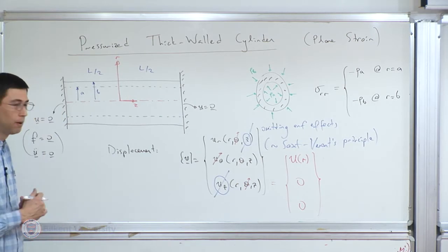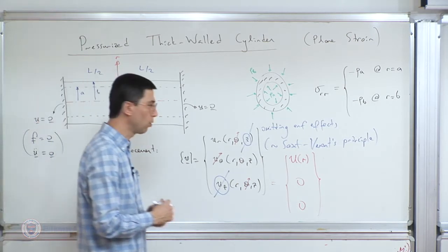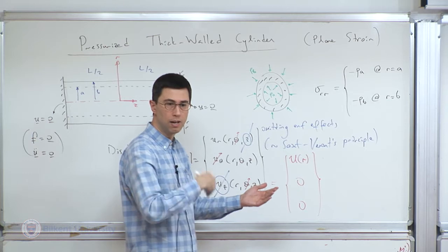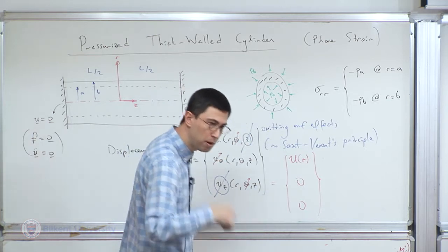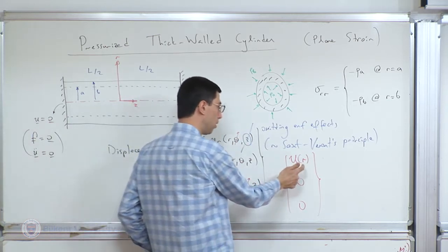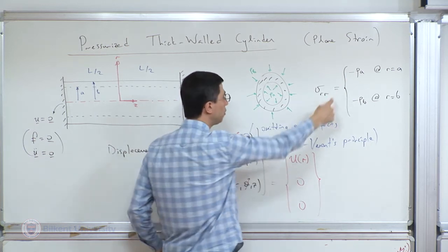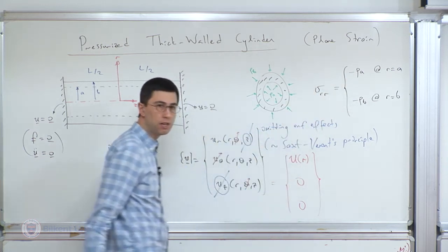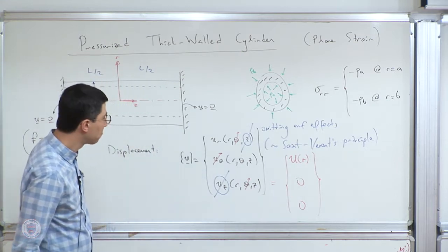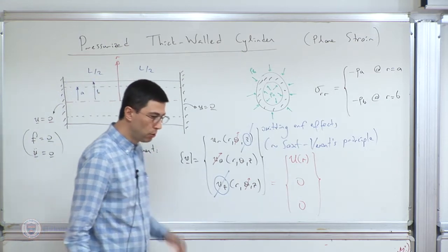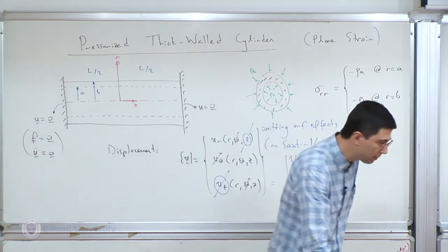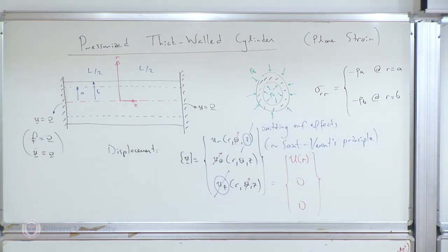This is the type of displacement that we would like to solve for. I'll calculate the strain, calculate the stress, invoke equilibrium, and thereby close the loop to find the general form of U. Then we're going to invoke the boundary conditions to find the constants that appear in that solution.